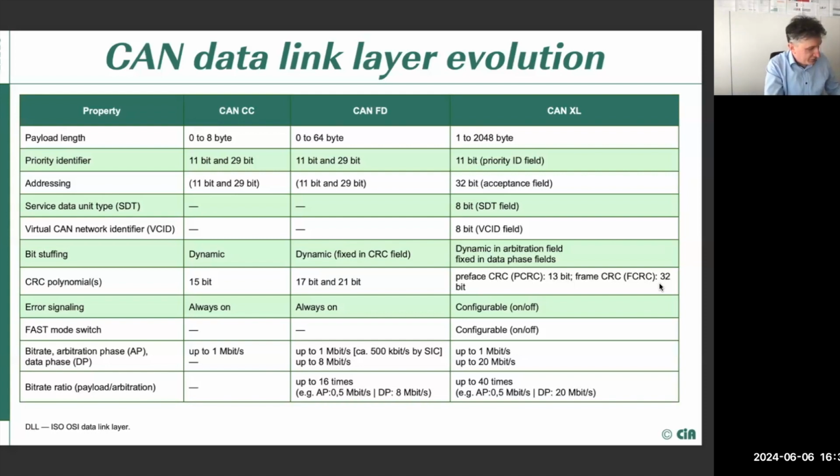There is necessity actually to put this into a certain condition. At a certain condition, sometimes the driving to the recessive edges could lead to several recessive edges occurring, so the devices wouldn't know if they have to synchronize on this error signal or not. So in this case it is possible to switch it, it has to be switched off.